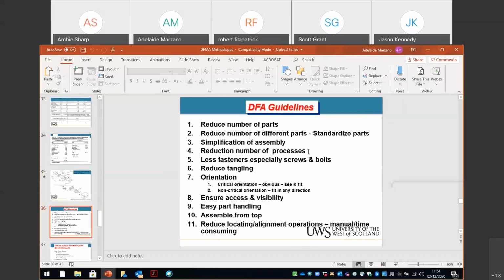I suppose just that with the difference in the two fish plate designs, one can be installed in either direction, and one has to be installed in a particular direction, because the stiffeners are on one side of one of the fish plate designs, but they're kind of symmetrical on the other one. Yeah.